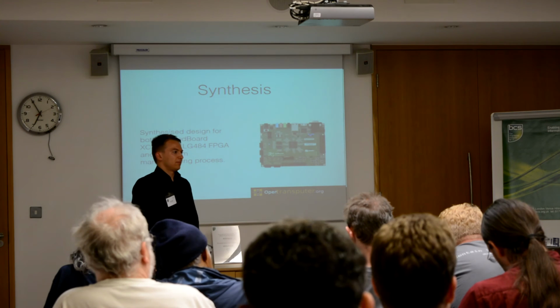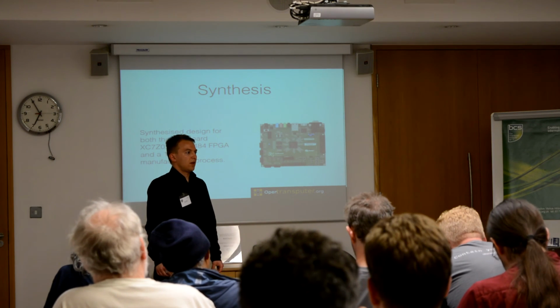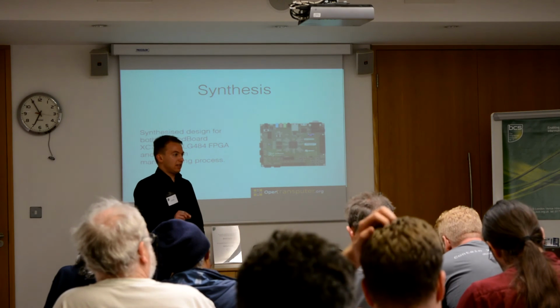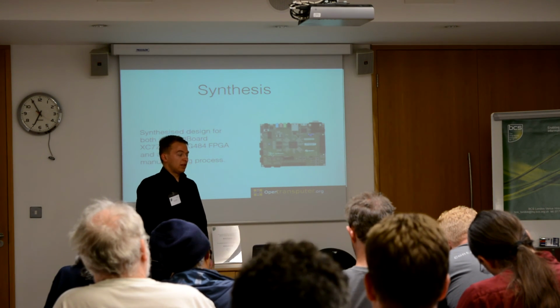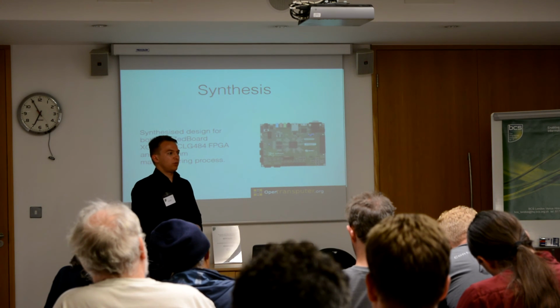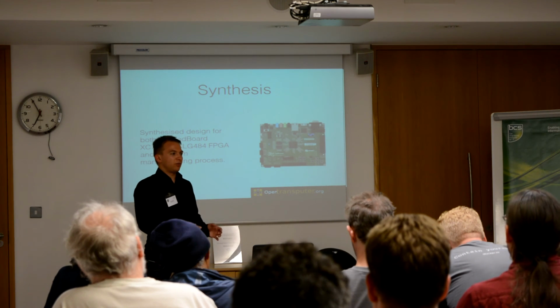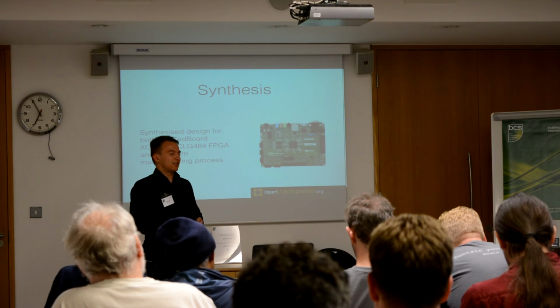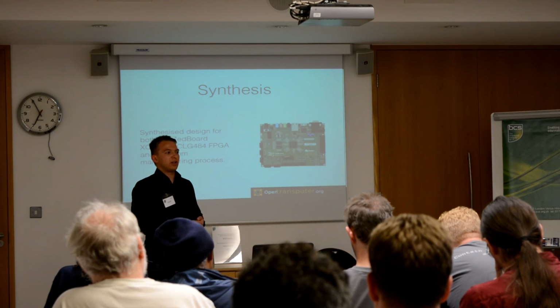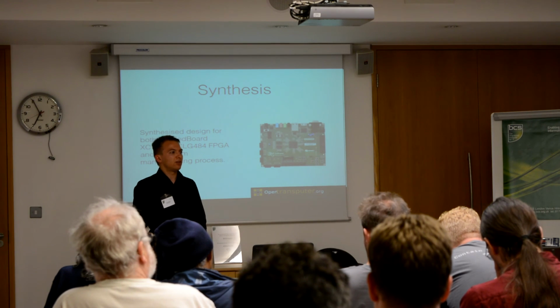What kind of clock speeds do you get? And do you have any thoughts about how to reduce the cycle time? Do you mean clock speed in the FPGA? Yeah, the processor. So with the FPGA we get about 42 megahertz on the set board. With the actual manufacturing process we haven't fiddled around with that much. If you did optimize it, we hope we could get up to maybe 200 megahertz. That would be the sort of range we're aiming for.